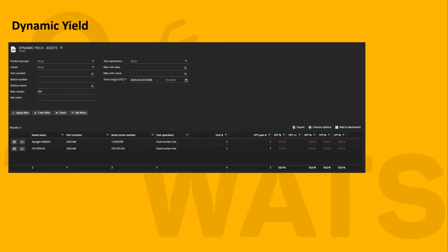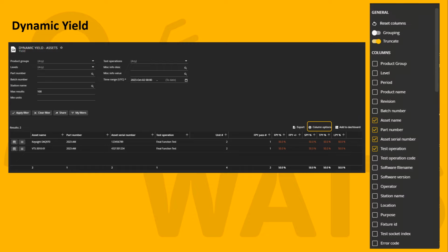In the dynamic yield report, we can add the asset name and asset serial number to the columns. Now, let's do that by clicking on column options and checking the boxes asset name and asset serial number. As you can see from my example, I've dragged asset name to the beginning, but I want the yield sorted on part number as well. So I have asset name, part number, serial number, test operation, the number of units tested, the number of units passed in the first run, and my yields displayed.